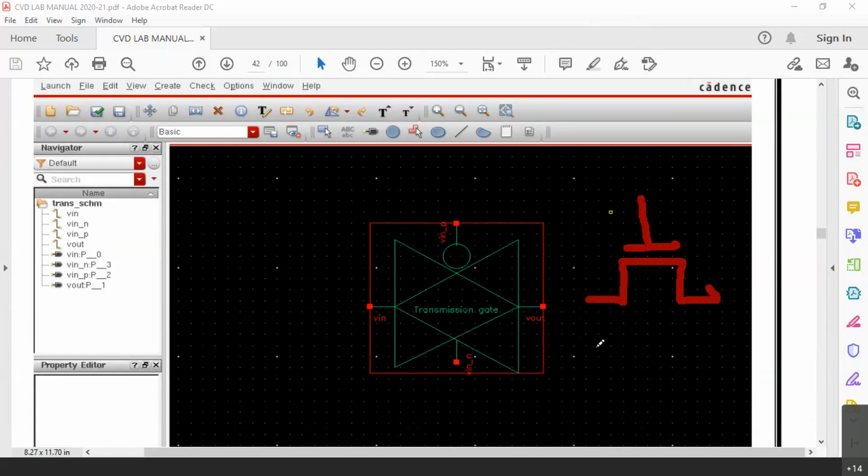Now, in this transistor, MOS itself is there, because the upper topmost layer is metal, source and drain are metal. So this is now at the top, metal. Then you have oxide, then you have semiconductor below. At the top you have metal, then you have oxide between the gate and the channel, then below, the substrate is semiconductor, so you have metal, oxide, semiconductor. And it is a field effect transistor. That way, whoever made the symbol for MOSFET is also a genius.